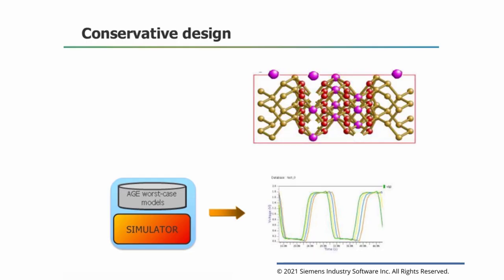The degradations are derived from simple aging experiments conducted on a few pilot devices. By applying very high bias conditions and temperatures on a small sample, the degradation of threshold voltage and mobility are measured and extrapolated. Then these values are applied to all devices, and the design is expected to work properly in all corners. These measurements are usually done and provided by your selected foundry.